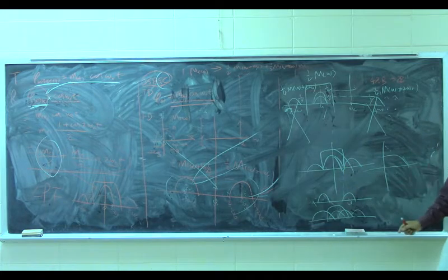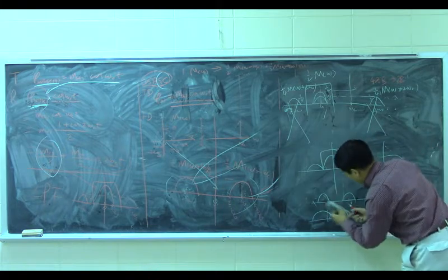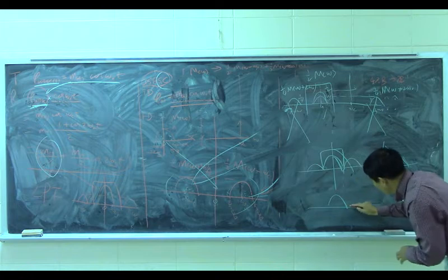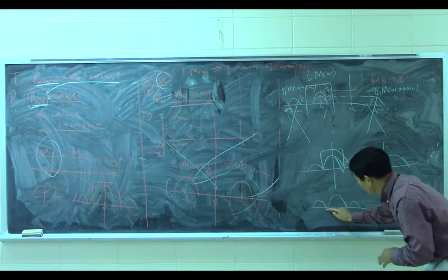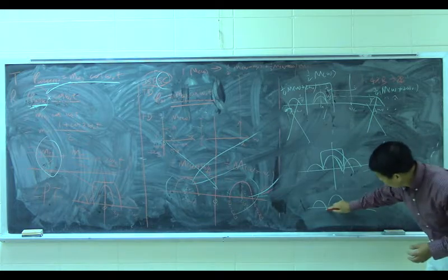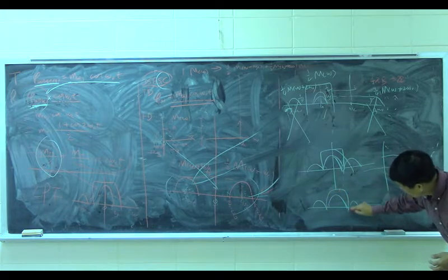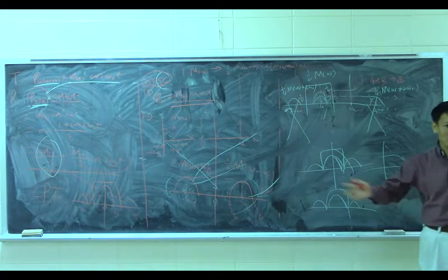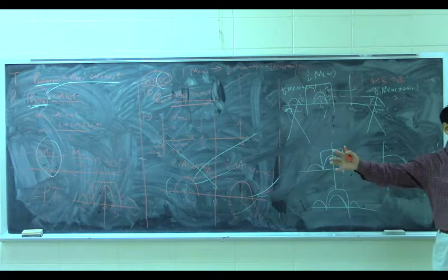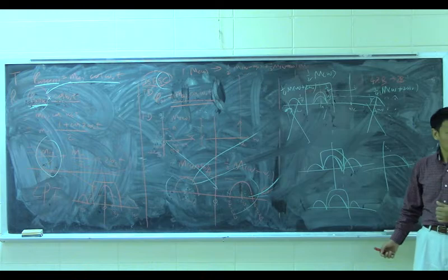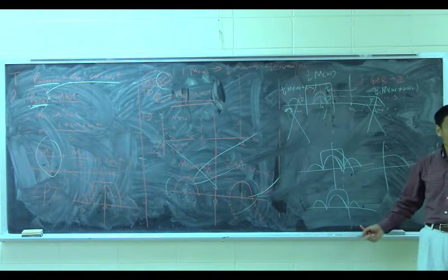So okay, I'll give you a little, so it will be like this. I'll give you something like this. There's a gap between this. Yeah, they can do this, but their low pass filter needs to be like this. So they need to use a lot of orders. For example, Butterworth filters maybe like 10, 20 orders make the circuit a lot of trouble. So they want life easier too.